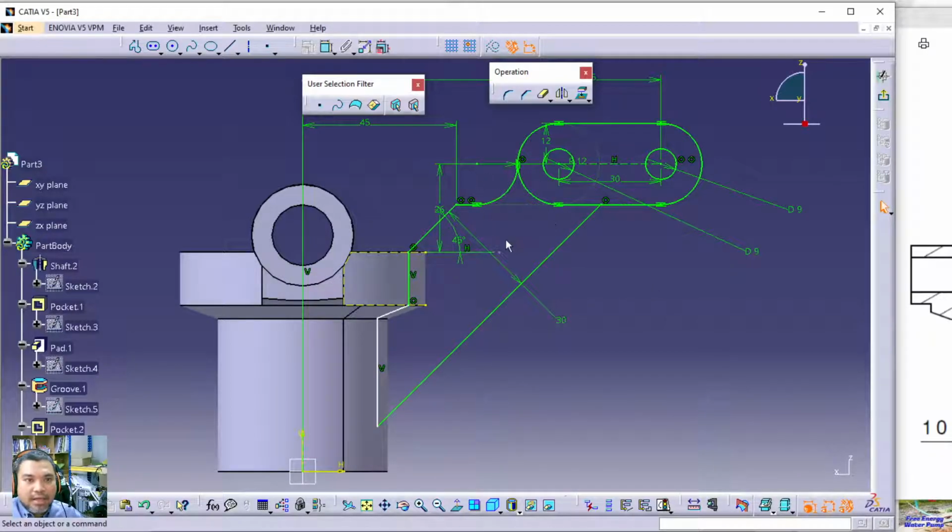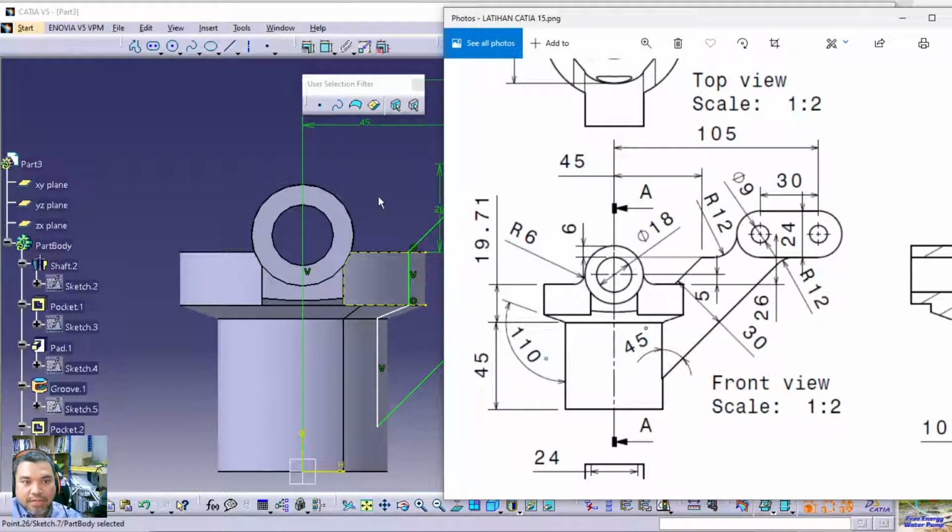Sorry, I forgot to make a fillet. Where is the fillet? The fillet over here, corner, here to here. But the problem is again, they are still missing something. So I don't want to make something like that. So just make another circle. Oh, delete this one. You need to make a free circle, this one with a radius of 12.